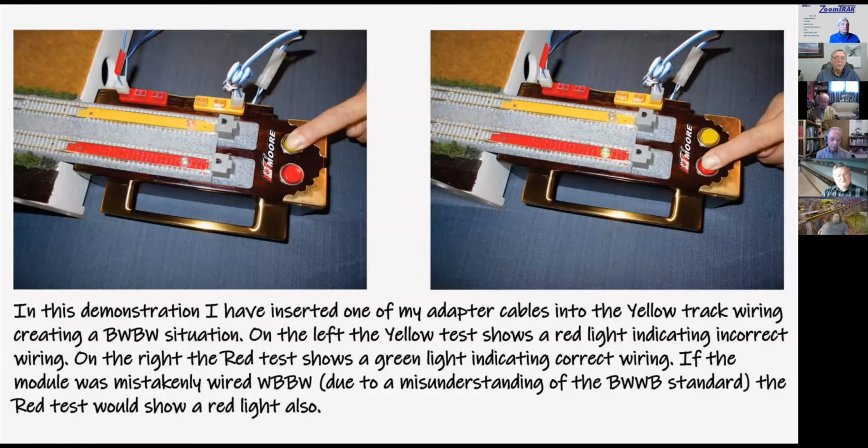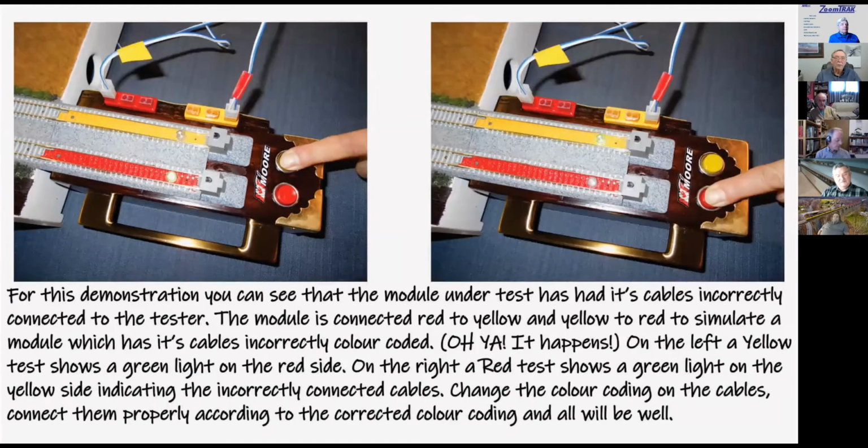In this demonstration, I have inserted one of my adapter cables into the yellow track wiring, creating a blue-white situation. On the left, the yellow test shows a red light, indicating incorrect wiring. On the right, the red test shows a green light, indicating correct wiring. If the module was mistakenly wired white, blue, blue, white due to a misunderstanding of the blue, white, white, blue standard, the red test would also show a red light.